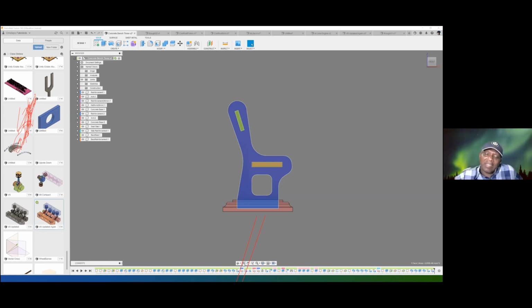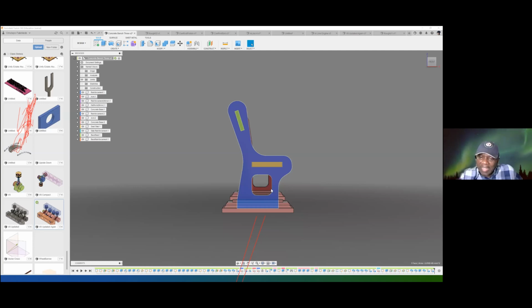Your camera is set here to orthographic. So let us go and change that camera setting to perspective. If we change that camera to perspective, you can see what has happened immediately is that you can see through to the other armrest, because your vanishing point now is no longer at infinity. So there are converging rays of light, and because of that, if you look carefully, you will see that some part of the other arm is also showing around here. You can see the other side of the armrest here. So that is your perspective.